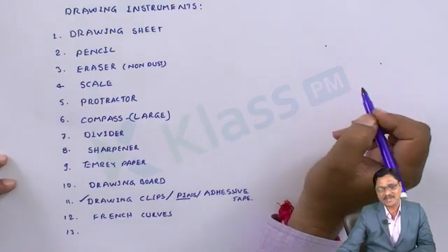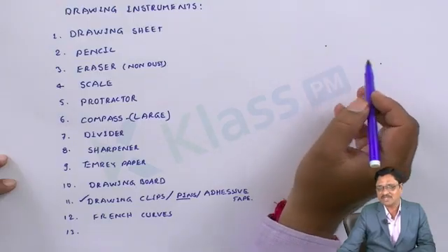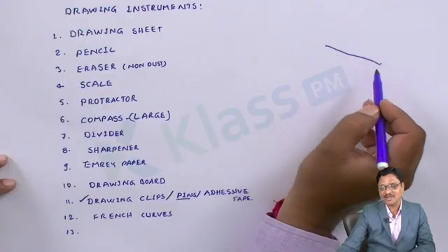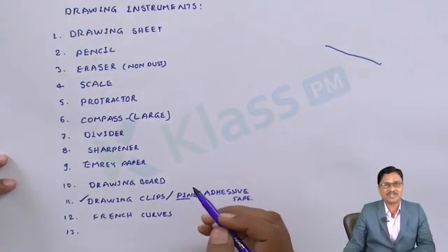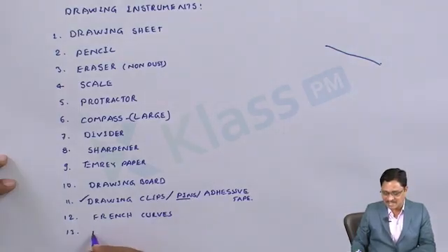On the edge of the irregular boundary, which exactly coincides with both the points, by taking the edge as reference you may join them, so that a little curve can be controlled by your hand. For that we are using the French curve. The same application we can get by flexible curves also.